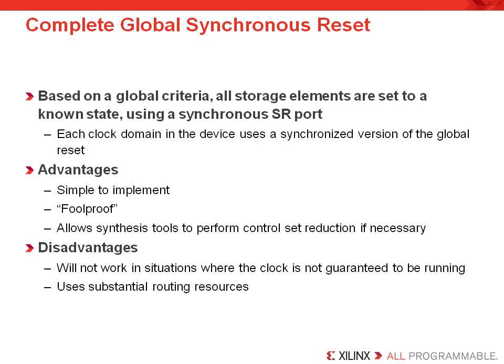Now, keep in mind that as part of the configuration process, we mentioned that a global reset is executed on a separate routing resource. So what we're really talking about here is, in addition to that configuration and reset, the use of a global synchronous reset. So in general, we would tend to discourage this if at all possible, simply because it sucks up so many routing resources, and the fewer routing resources you have, the fewer chances you have to be able to meet your timing objectives.